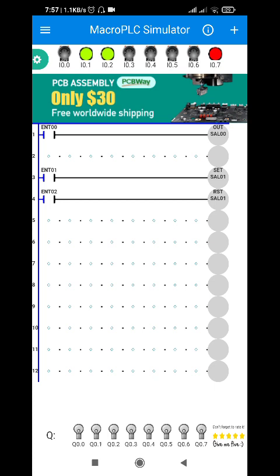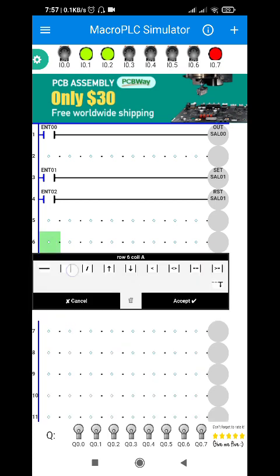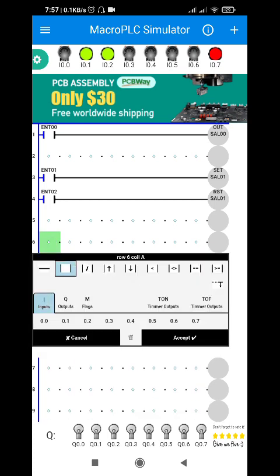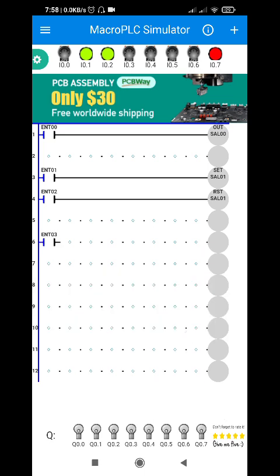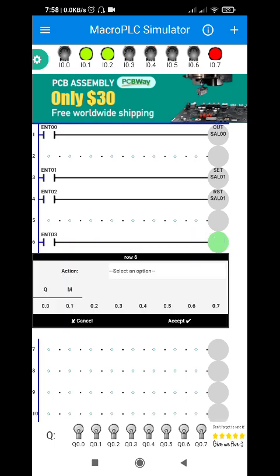And that is when we use the latching circuit or the latching program. So for that, we're going to use the relay function. So how do we do that? First, I'm going to create another program. And I'm going to use the button that I have not used so far. So I0.3. And I'm going to create an output using a Q0.3.